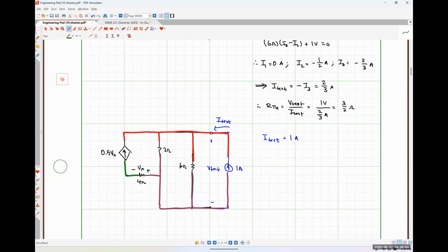Okay. There are no voltage sources, so I don't have any voltage relationship equations or any voltage sources to take into account for where I choose my ground. So realistically, I could put my ground pretty much anywhere. I'm going to choose the purple node, so the bottommost node, as my ground, just because that will let me see it here in a second.